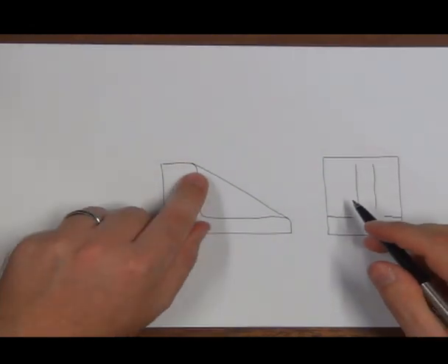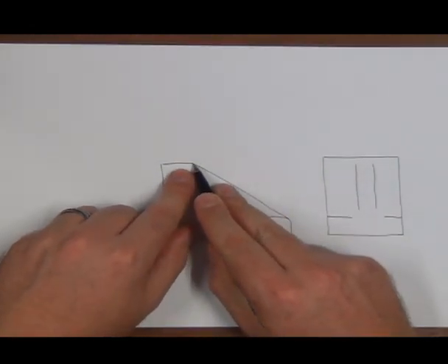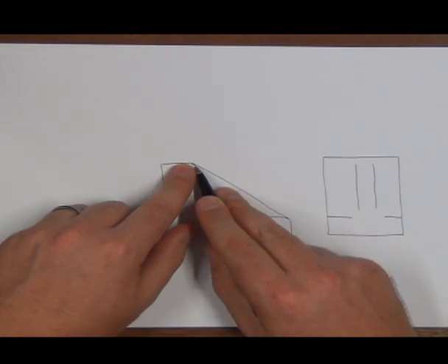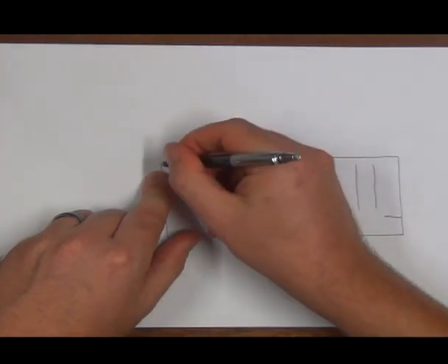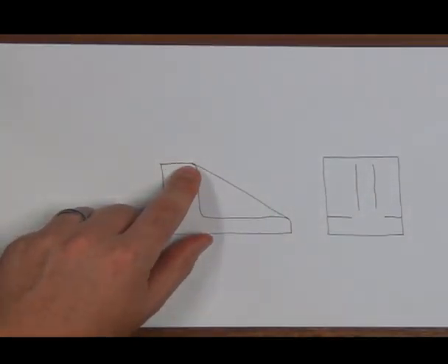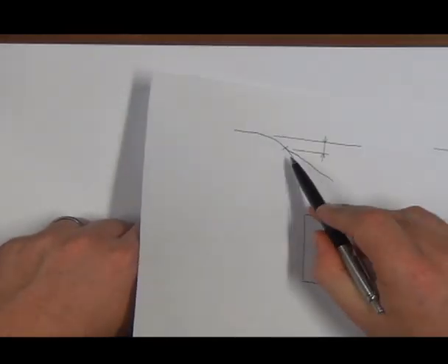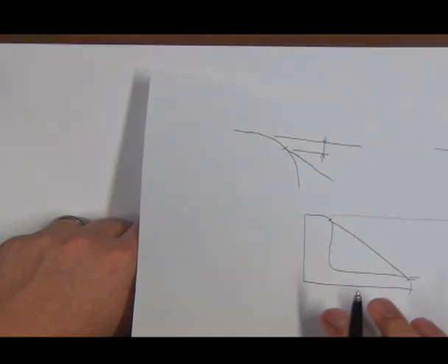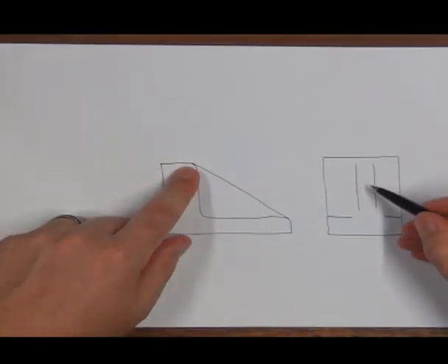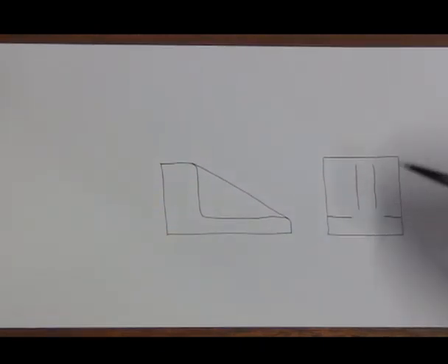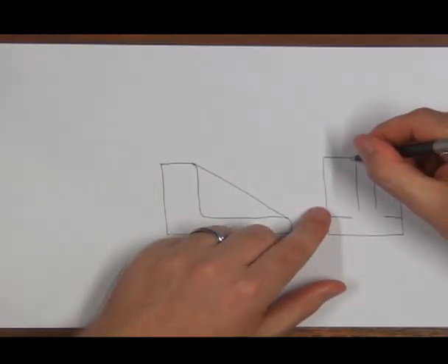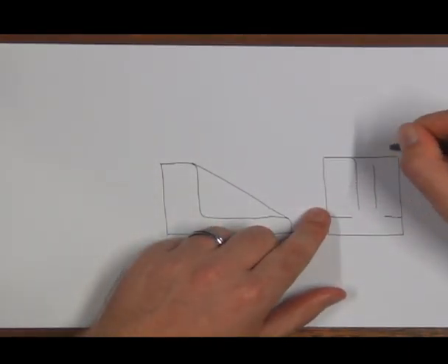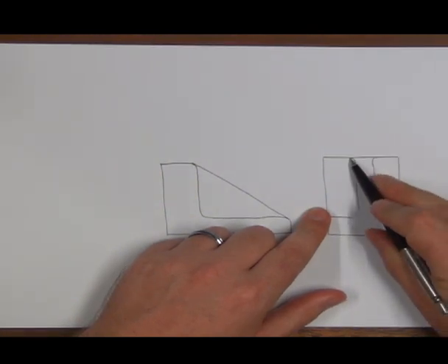Okay, let's do the top one first. Because it's a small radius, I can't visibly see that there's a height difference between the point where it touches and the actual top of the component. I know there is a physical height difference, so if I zoomed in like that, I will maybe still see the height difference, but in this view it is too small to show that difference in height. So what we do to show that it's still nicely blending onto that surface, we still do the small radius, but it now touches the top line.